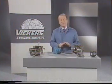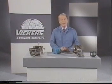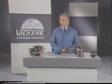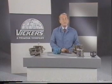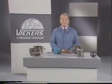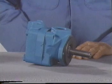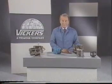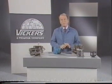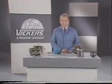Now, let's focus on two different types of balanced vane pumps Vickers currently manufactures. Both are similar in operation but differ in construction and pressure capabilities. We'll first discuss the pump patterned after the original model patented by the company's founder, Mr. Harry Vickers, in 1925. Called the V20, it can be run at speeds as high as 3,400 RPM and pressures to 2,500 psi. These high-performance capabilities make it well suited to both industrial and vehicle applications.